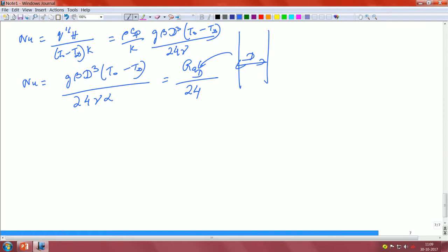Now, one other thing that is important is that here also we see that there is no Grashof number coming into the picture, it is still Rayleigh number with respect to d that we are concerned about. Now, of course all these expressions are valid if and only if the entrance length yt that we have said earlier is less than h. This is the critical condition, right.